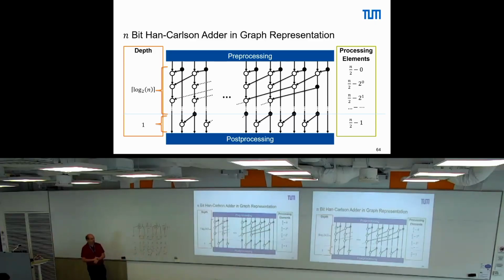Okay, so a carry-save adder adds up 3 bits and compresses them into 2 bits, and then at the end we need to transform back. This transform back can be done with any of the 2-input adders we had before. You can put a Kogge-Stone adder here, you can put a ripple carry adder here, whatever you want, because you have 2 inputs that you want to add up. You just need to connect correctly. So these 2 are effectively then one input for the next adder layer.